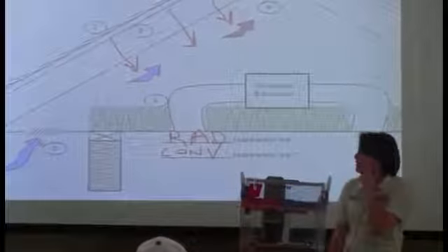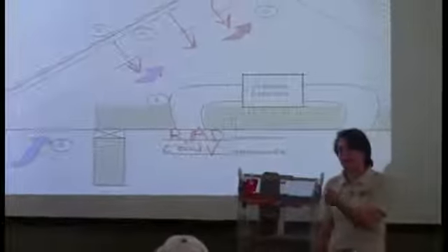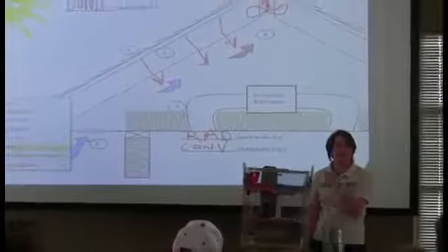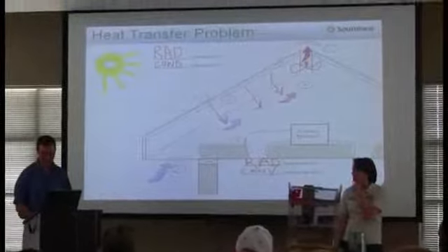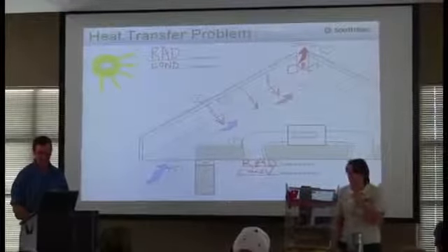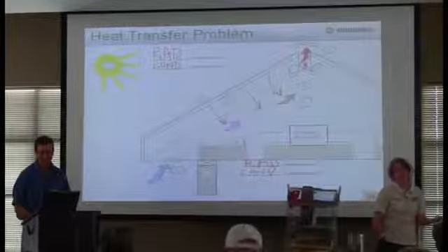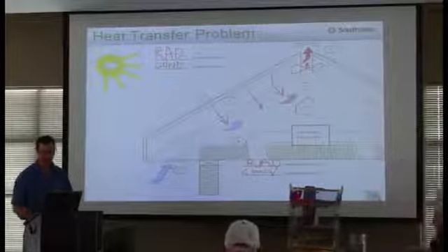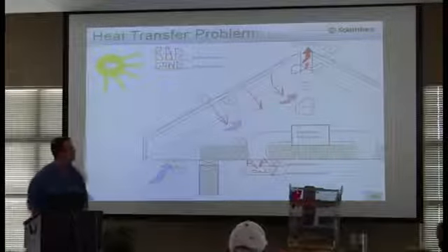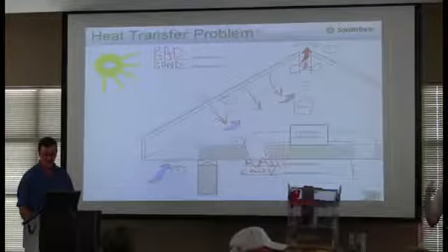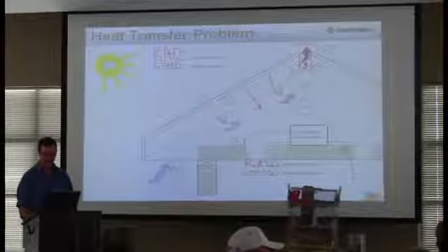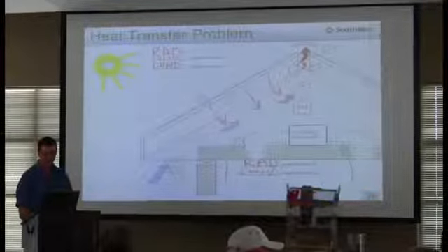Oh wow. You mean we're cooling our attic with our nicely conditioned air from our living space? Sadly, yes. And then blowing it right out. So that means, yeah, we totally are cooling our attic. But how are we cooling it? Well, partly through some ventilation from this side, but also the conditioned air that we had inside our living space is also cooling off our attic.